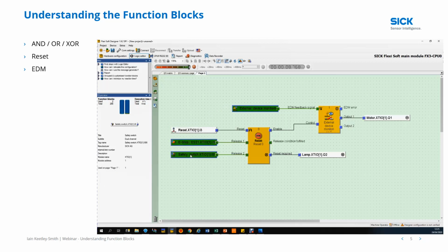Now I put in the e-stop and safety switch, and get my reset required. I have to just stop the simulator, press the reset, step at 200 milliseconds, and then release the reset push button, and the motor will come on. Now that's come on, that has to go off. So it always has to be the opposite. Now it'll run fine. Now if I activate an input, the motor will go off, and what we're going to do is not change that.